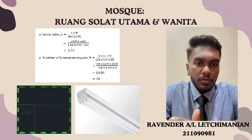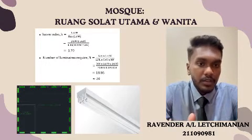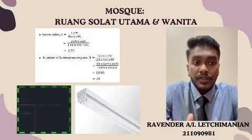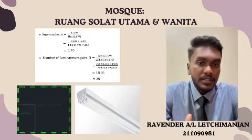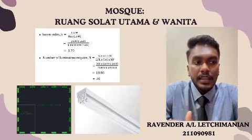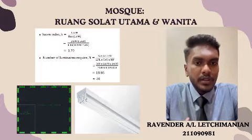Suitable for a normal room, according to the Malaysia JKR standard, the required illuminance is 300 lux with a maintenance factor of 0.8. We use 7500 lumen lights, specifically the TLD standard fluorescent lamp, which is 3 times 36 watt, as indicated in the datasheet. Now let's see the lighting calculation for the Ruang Solat Utama and Wanita.